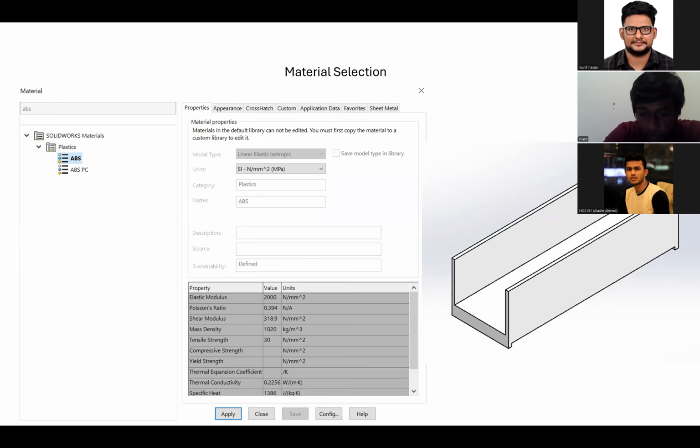For the material selection, after defining the dimensions, we selected the material for the prototype to be printed. SolidWorks has its built-in materials library and database. Our targeted material for this project was ABS, which is a common impact-resistant engineering thermoplastic, often used for 3D printing. The designated mechanical properties were reviewed in the default library in SolidWorks.